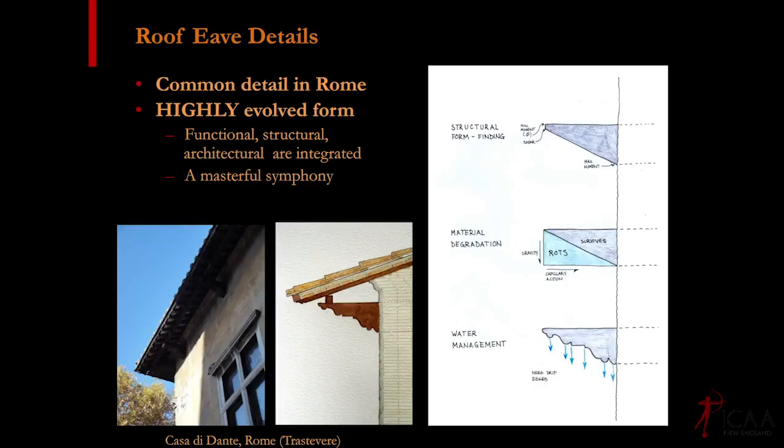And I'd also want to point out that the rafter overhangs it, the stop, which keeps the decking from sliding off, overhangs that, and then the clay tile overhangs that. So everything overhangs everything else. As water comes down off this roof, it's not curling back around and getting this wet, it's clearing it straight off. And if you think about this angle, even in a 45-degree wind-driven rain, which is pretty severe, this never gets wet.